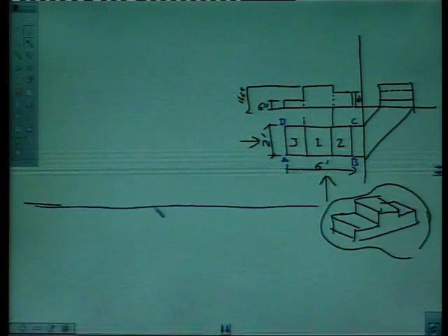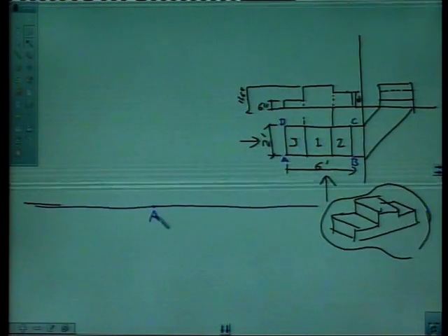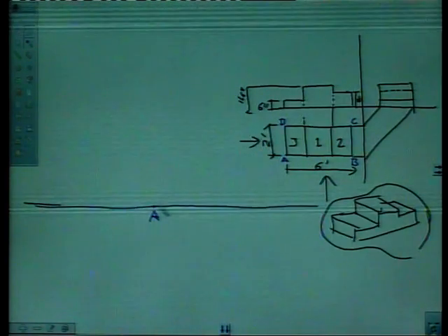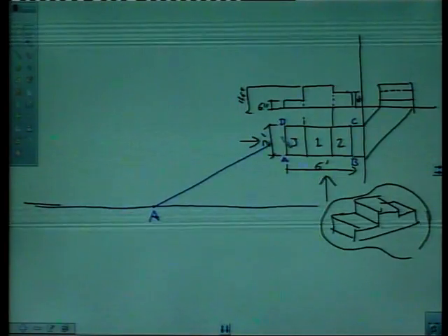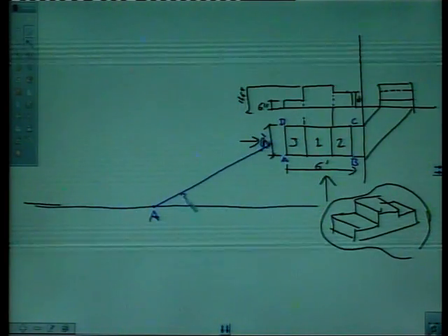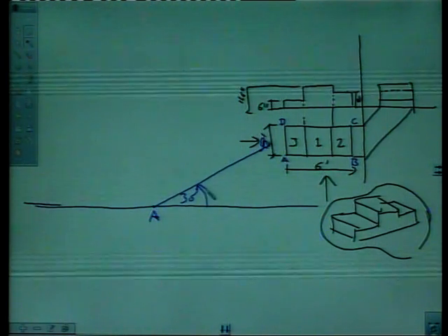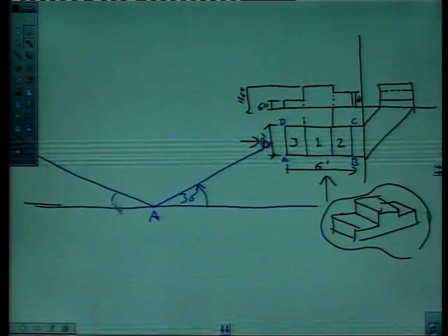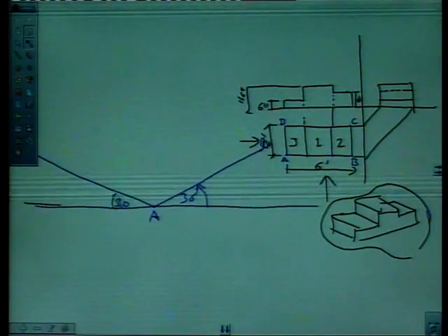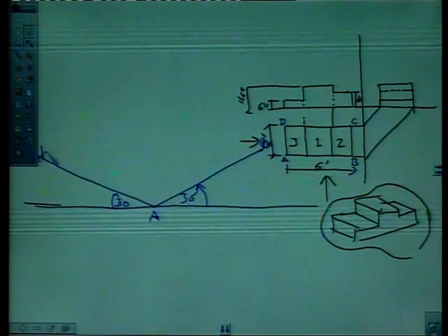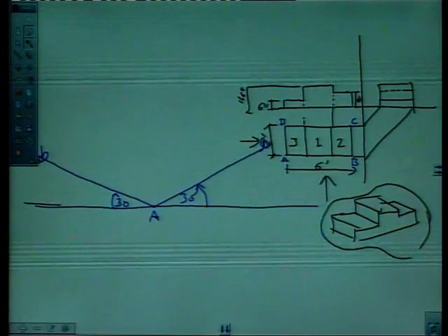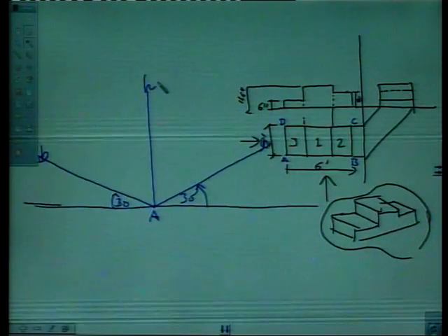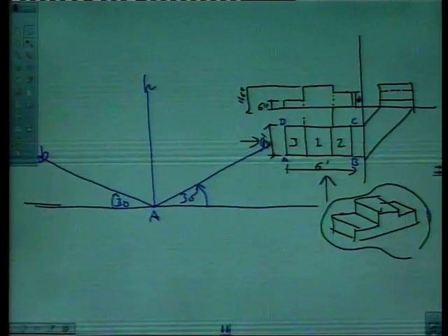Say I start from point A, say this line represents point A, right. First of all I will draw a line for marking lengths of the object, right, at 30 degree. Similarly for marking breadth, I will draw the next line, again at 30 degree. For drawing heights, I will draw a vertical line from point A like this. This line will represent the height of the object, right.